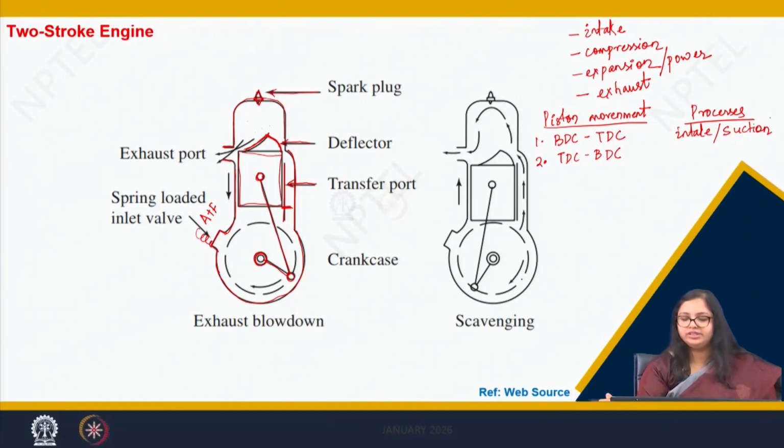Now when the piston moves from TDC to BDC, that is top dead center to the bottom dead center, my transfer port opens, and the air plus fuel mixture gets into the cylinder.